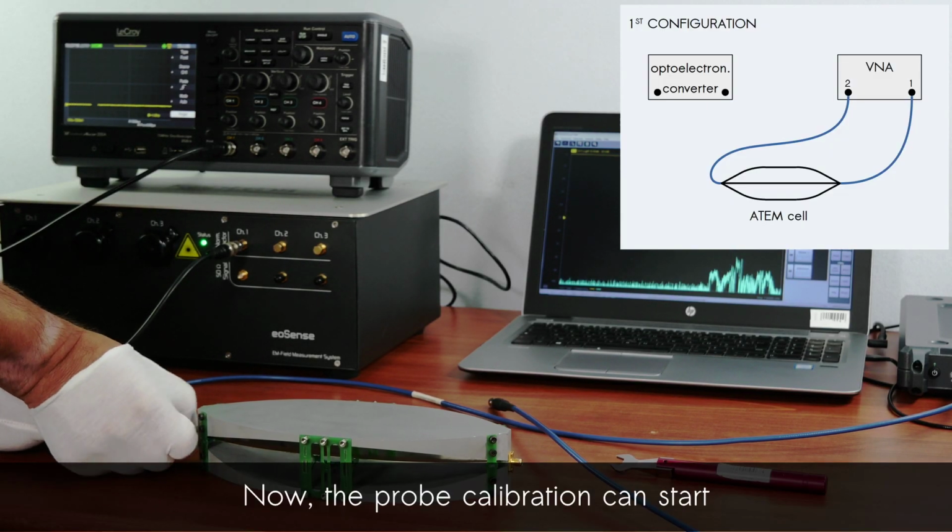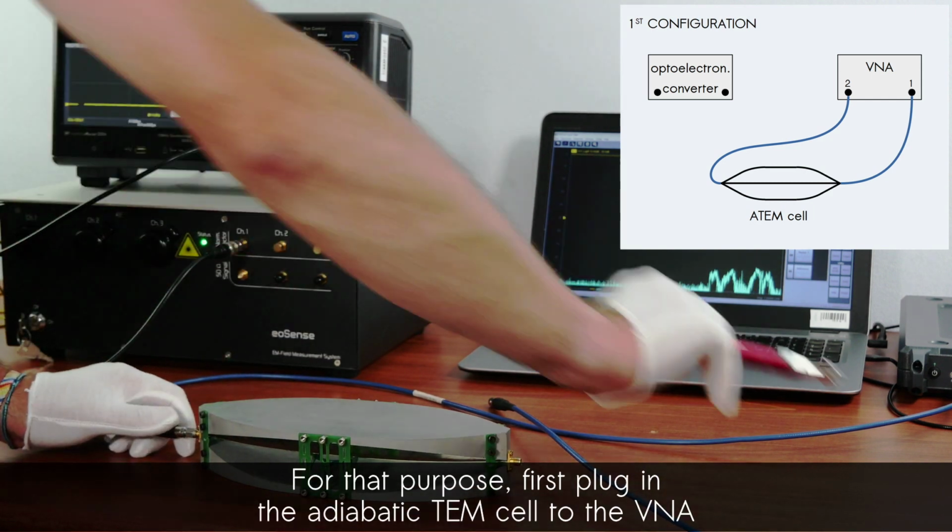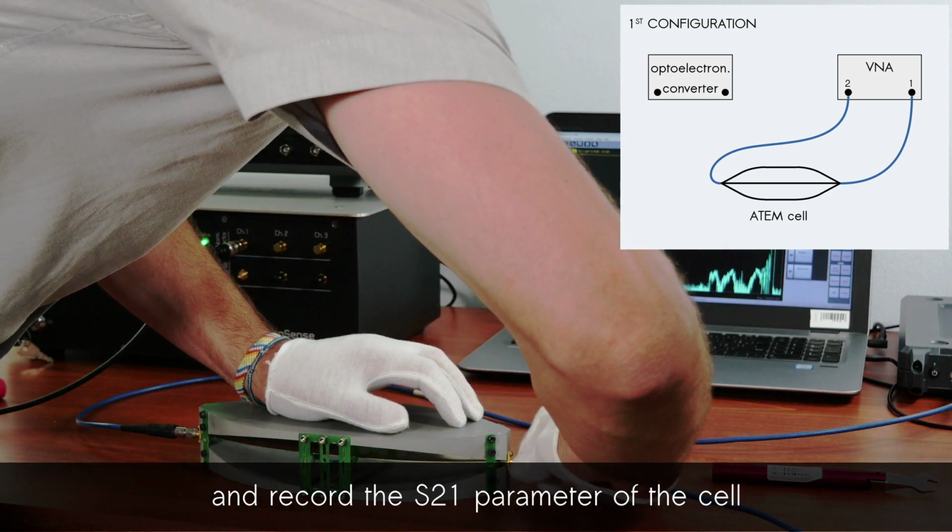Now, the probe calibration can start. For that purpose, first plug in the adiabatic TEM cell to the VNA and record the S21 parameter of the cell.